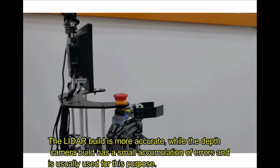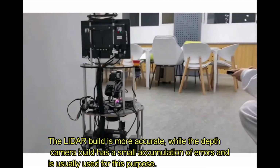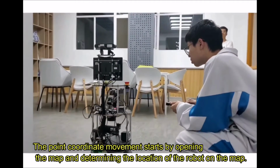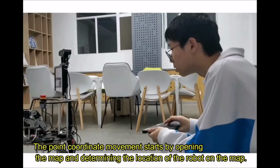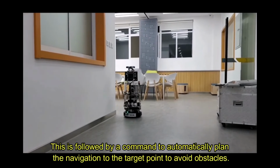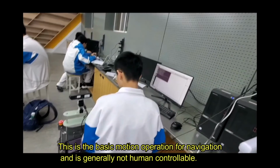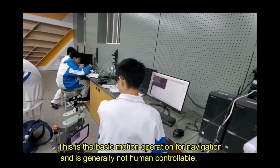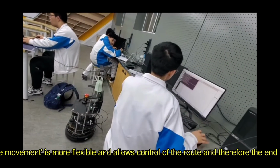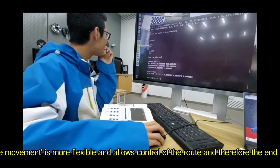The lidar map is more accurate, while the depth camera map has a smaller range and is usually used for this purpose. The point navigation movement starts by opening the map and determining the location of the robot on the map. This is followed by a command to navigate automatically. This is the basic motion operation for navigation and is generally not human controllable. Planar translation is more flexible and allows control of the route and therefore the end point.